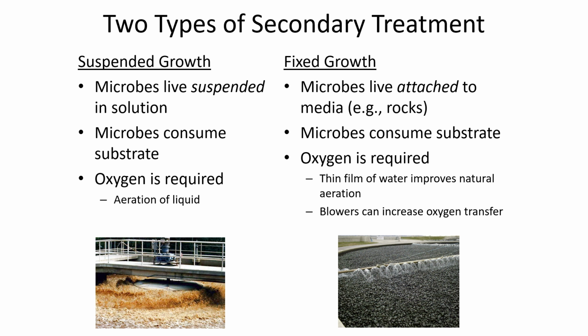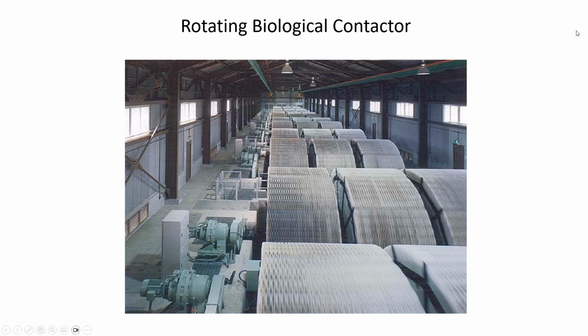The water is moving, but the microorganisms are stationary, and they take the food from the solution being sprayed on them. Then we don't have to pump air, or if we do, the ventilation requirements are much easier than if we had to dissolve the oxygen into water. So we're going to talk all about fixed growth for the remainder of today's class time.